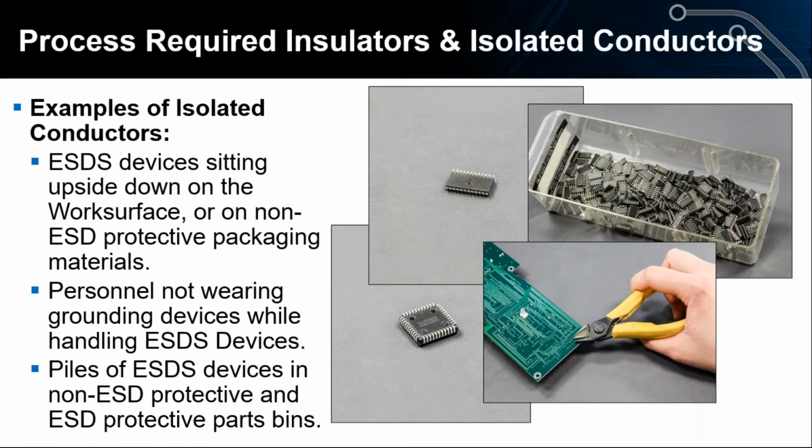So especially for those last three types of cabling, testing types of products, really there are two choices. The item needs to be grounded to less than 1 × 10⁹, or using a contact or non-contact voltmeter, you need to measure the charge on those conductors. And the upper limit of acceptability is 35 volts, positive or negative.